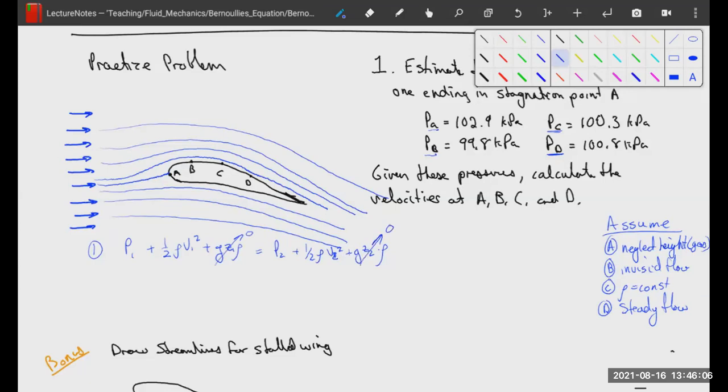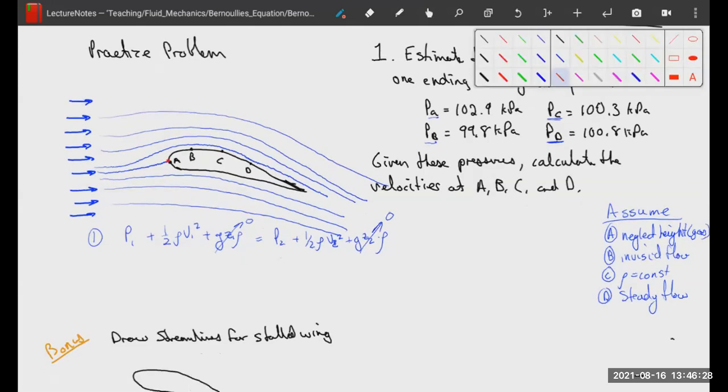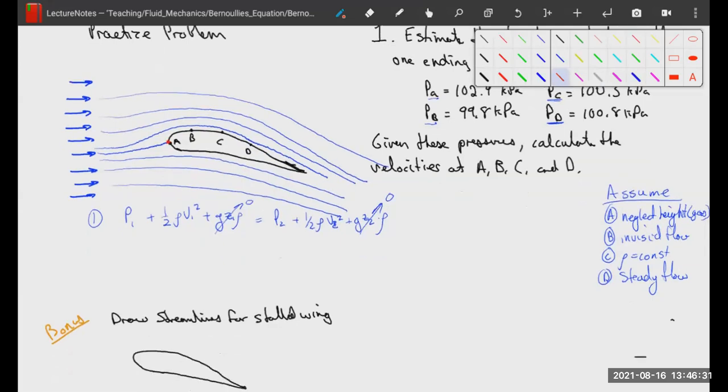And actually now we're going to draw a streamline. And this is where, again, remember we talked about how we're not necessarily using all of the assumptions in Bernoulli's in their purest form, right? Bernoulli says you have to be on a single streamline, right? Well, what we're going to do is take a quote unquote streamline, starting at our stagnation point or right next to it.